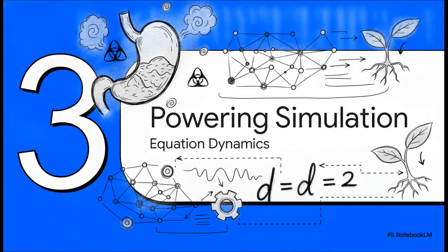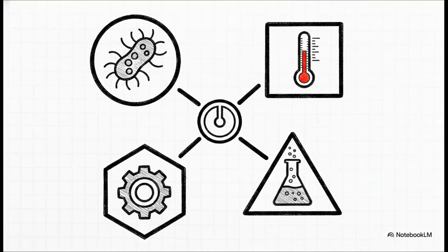That leads us into Section 3, powering the simulation. So, with the biological parameters mapped, the software has to run continuous differential algebraic equations to simulate the passage of time and dynamic plant changes. To pull this off, the platform utilizes specific interconnected classes like the biochemical and physicochemical classes. But you really want to pay attention to those bottom 2 elements, pH inhibition and the K function. These ensure realistic environmental constraints. If the virtual pH drops too low or there's a sudden temperature spike, these functions step right in and accurately throttle the virtual microbes. It simulates a real-world system crash before it ever happens in reality.